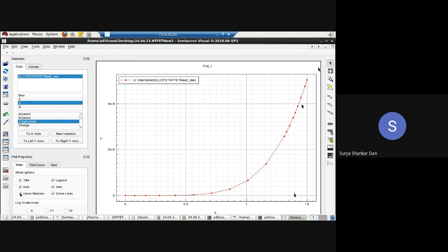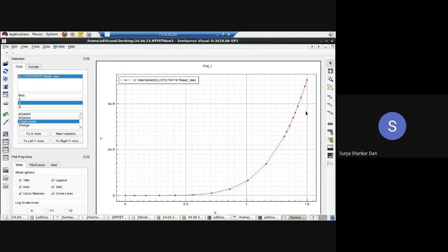Now the point is, why is that an important part of understanding? Because remember, when you are changing a little bit of oxide thickness, why? Remember, the oxide thickness she has used is how much, Aditi? 3 nanometers, right? Yes, sir. 3 nanometers. So how can you always ensure that your oxide thickness will be exactly 3 nanometers? You can't ensure that every transistor will always have 3 nanometer oxide thickness. It will be 3.1, 3.2, it can be 5 nanometers also. The moment it is 5 nanometers or less than 3 nanometers, your simulations will not work.